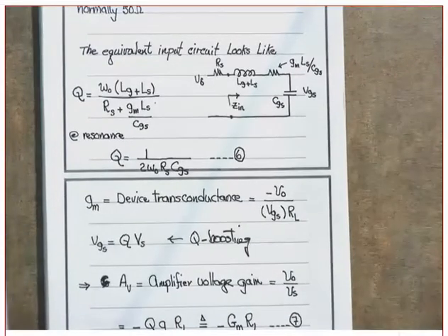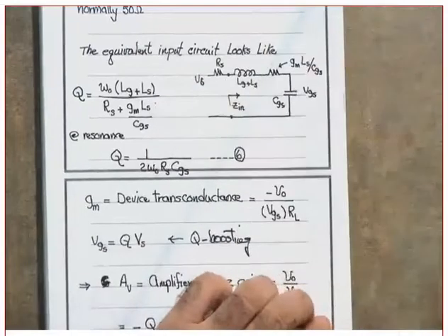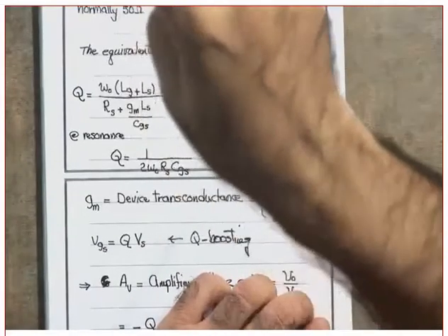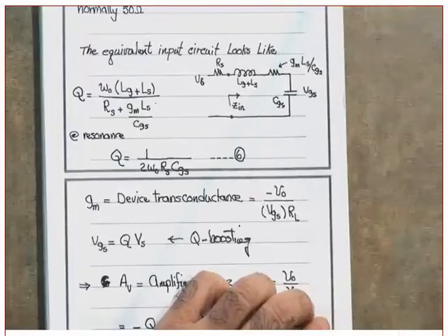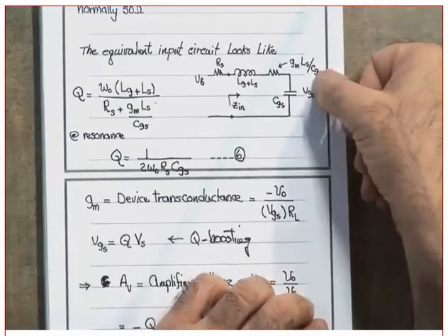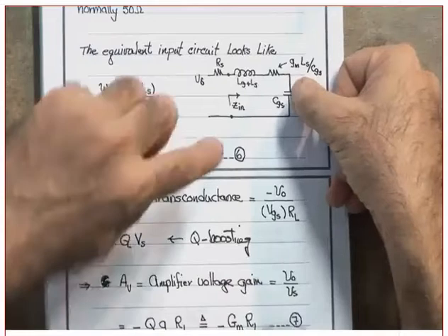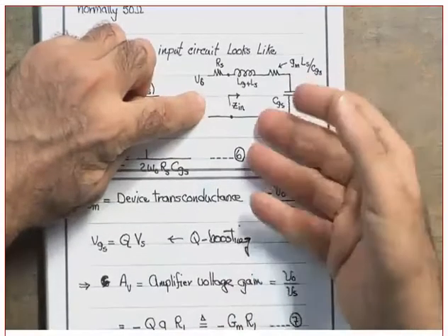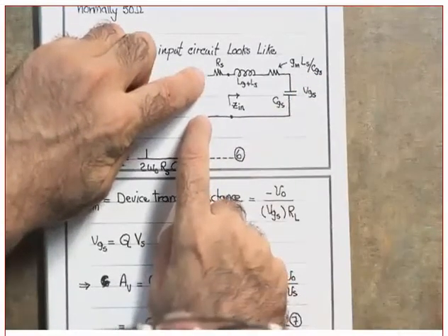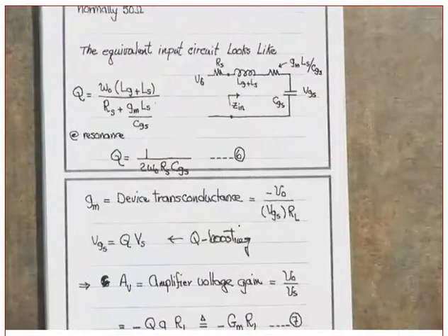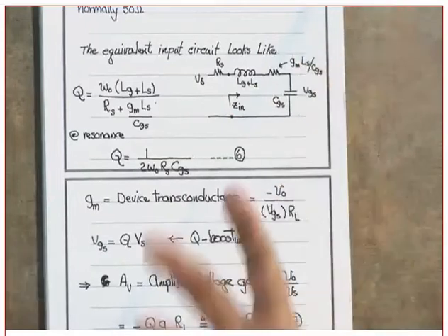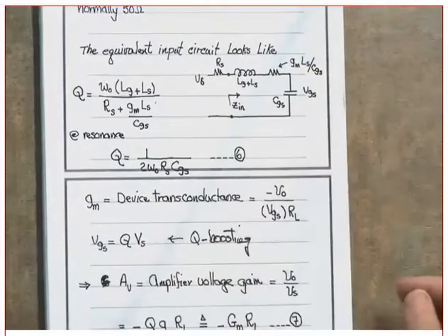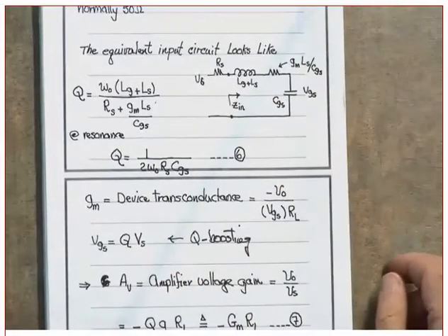You lost me here, I think. What are the characteristics of the device? The output characteristics is ID versus VDS for constant VGS. That VGS is going to be Q times as high as this one. Which means I need to make sure that the voltage here does not have a large swing. Why? Because if it is a large swing, it's already going to be boosted by Q. Do you understand that or not? And it might result in breaking the device itself. Clear?